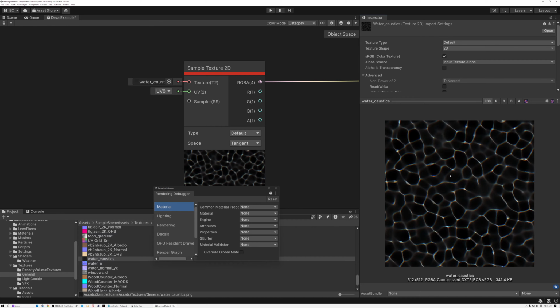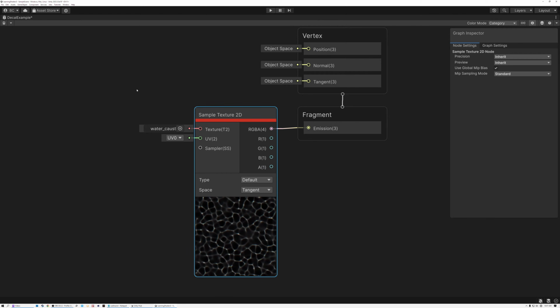And then after I generated it, I created a little bit of chromatic aberration by offsetting the blue channel up and to the left and the red channel down and to the right just by 1 pixel. And you can see that creates this kind of rainbow fringing, which is kind of a simulation of the light being split and scattered by the refraction of the surface of the water. So this is a tiling texture, and you can see here I'm just passing it into emission.